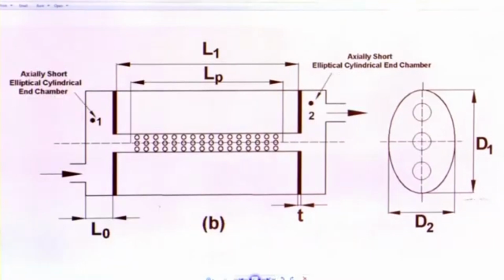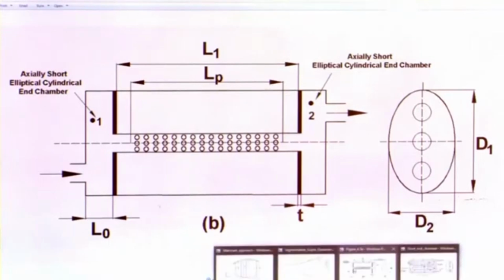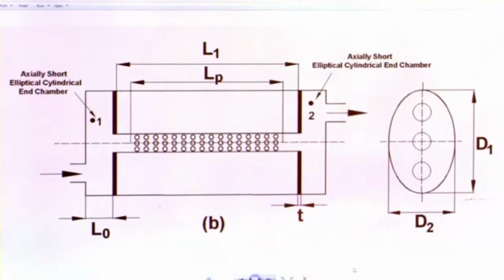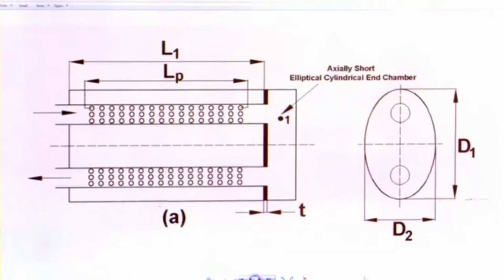So, such silencers are used invariably in a lot of modern day commercial vehicles, and the good thing about such silencers is that they are able to pack in a lot of transmission loss, good attenuation performance, even when you have limited space, because the waves have to go through multiple perforated pipes and there are a number of end cavities, quarter wave resonators.